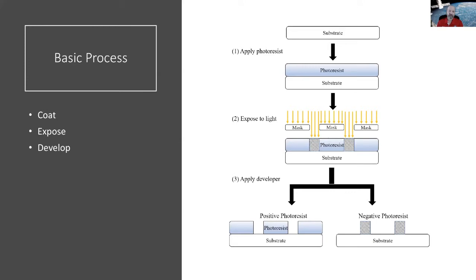The photoresist captures the ultraviolet photon through a photoactive compound, and a chemical reaction occurs which causes that part of the photoresist to become slightly acidic. Because it's slightly acidic, it can be developed out with a basic solution, which we call developer. So this series of steps is pretty typical for transferring your design onto the wafer.